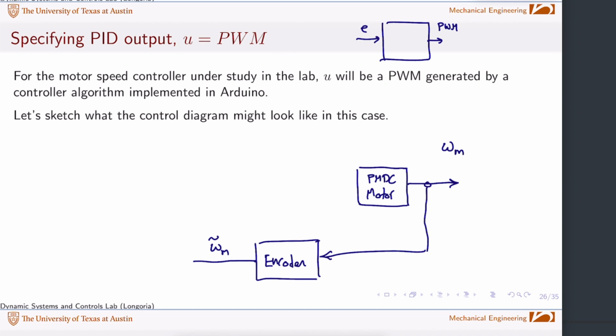By the way, I'm showing this with continuous time signals, but we know that all this is discrete time. So over here somewhere, we're going to be giving it a reference, and that same units is here, so we're going to have an omega m, and we call that omega m ref. You can designate that. And that's a plus always, and this is a negative. We always use negative feedback. Positive feedback can be destabilizing. You can read more about that somewhere else, or if you take a controls course, you can show why negative feedback is stabilizing and positive feedback is destabilizing, and so that's how we're going to generate some error.